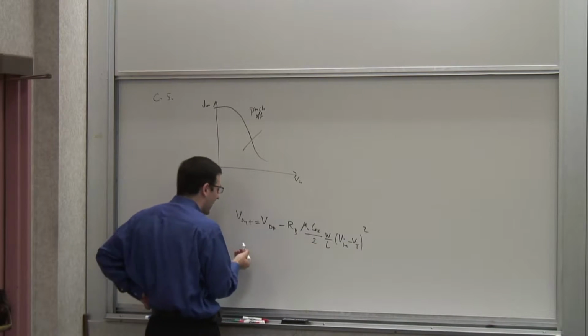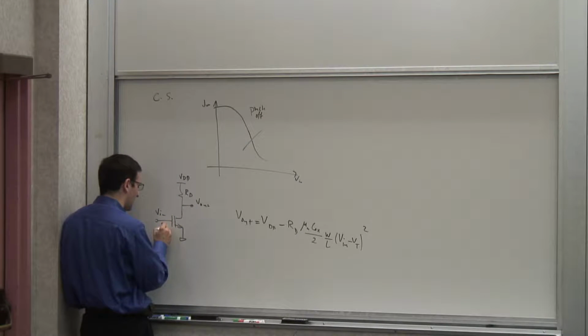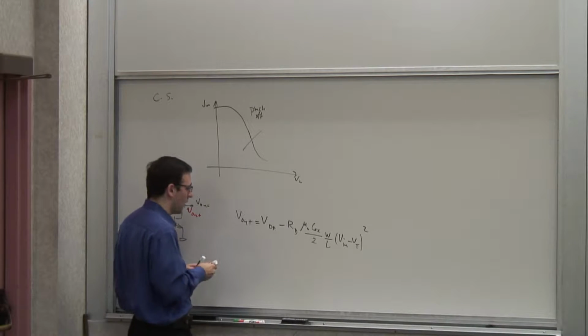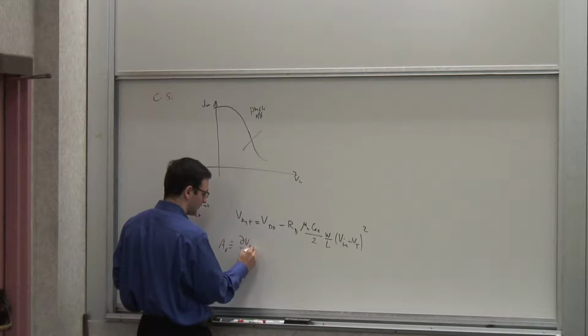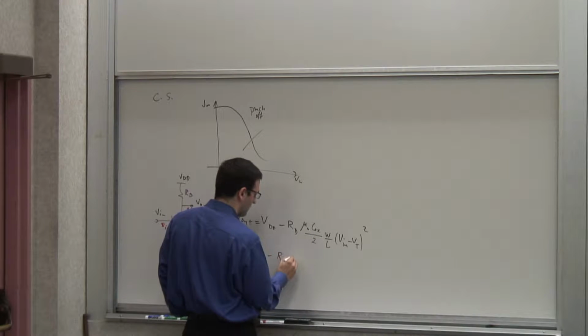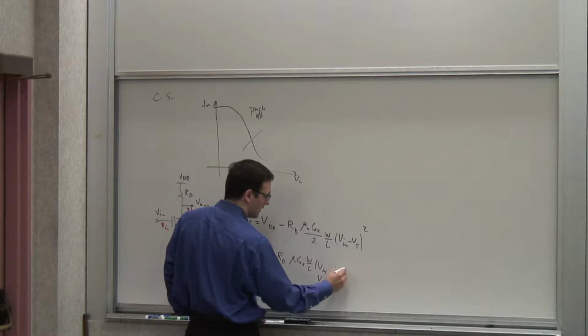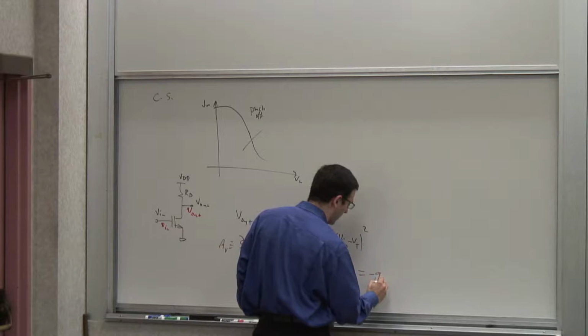And when we looked at it, we could calculate the small signal gain, basically the ratio of the variations between V in and V out, small perturbations on top of the operating point. You could define it as Av is dV out to dV in, which is basically RD mu n C ox W over L (V in, which is VGS, minus VT). And this thing was nothing but the gm of the transistor. So this is minus gm RD.